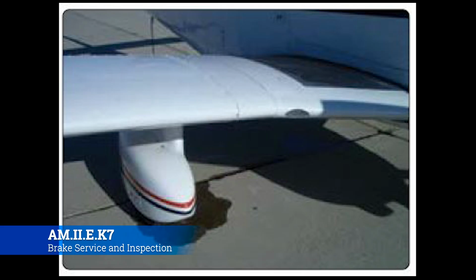I worked a deal recently where this exact scenario had happened, except on a Citation. What was going on is that they had flown into a cold area. The O-rings had shrunk, and then whenever they got back down to Texas, it got warm again, and they expanded back out. Well, that change in temperature caused the O-ring to crack, and then whenever they started to apply the brake pressure, the fluid started to slowly seep out of the line. So, something to look out for.